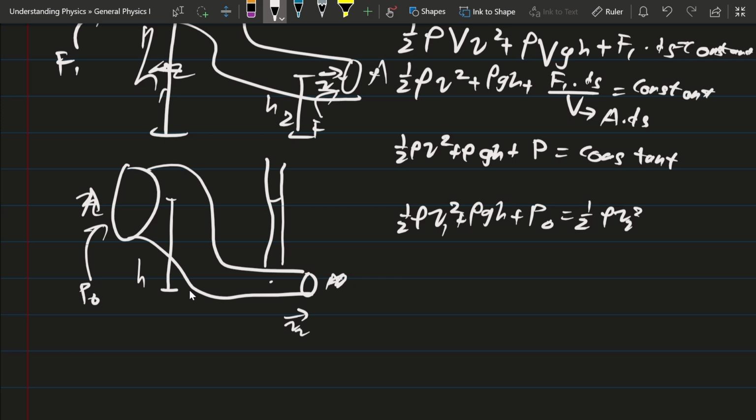Okay, what's the rho gh in here? Is it the height of this? No. In fact, the rho gh in here is actually 0 because the height is actually 0. But why do you need to add another rho gh which corresponds to the height of this small tube? Because it is actually measuring the pressure inside of this small tube. So what's the pressure within the small tube?